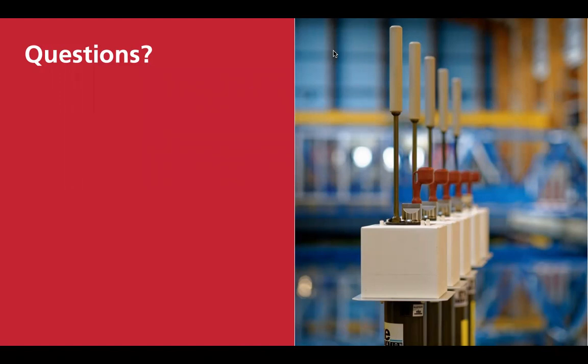Yeah, that's right, of course. Salinity is a derived measurement, but roughly speaking, if temperature is calibrated to 0.002 degrees, and conductivity is calibrated to 0.003 or less, you get about 0.003 accuracy in salinity. It depends a little bit on the water temperature, but for 15-degree water at 35 parts per thousand salinity, you would expect an error of about 0.003. Does that answer your question?